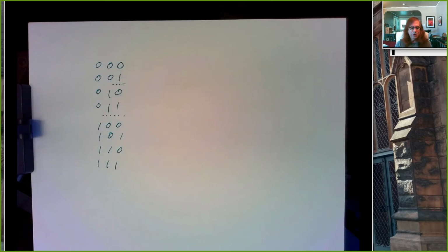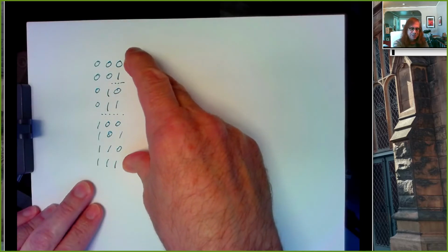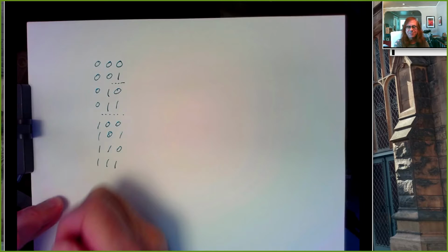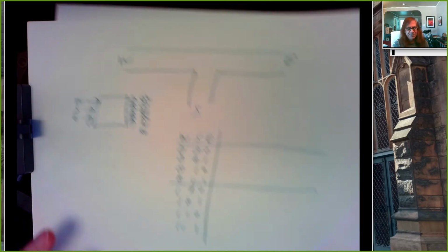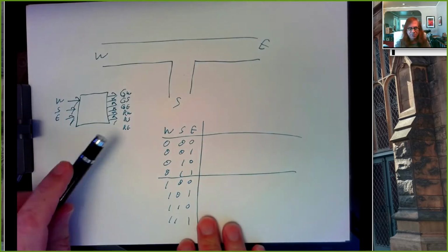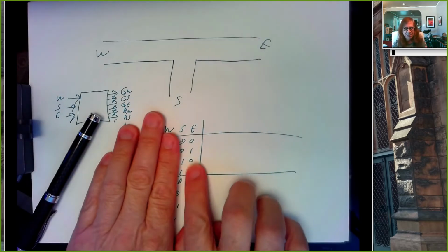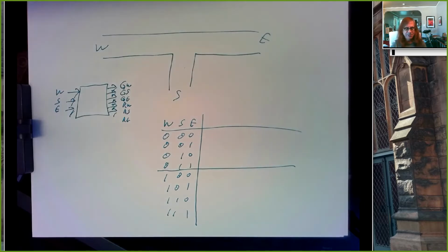To add one more bit, basically make another copy of your n-bit counting sequence. Put zeros in front of the first half, ones in front of the second half. That gives you your n+1 counting sequence. And eventually this becomes second nature, but until then, you can use this technique to go from 1 to 2 to 3 bits, or however many bits you need.